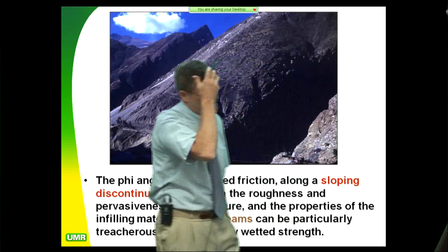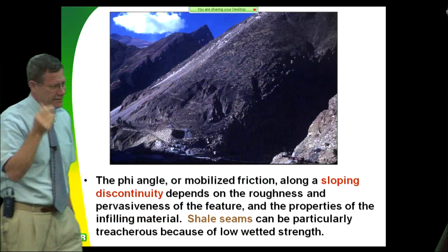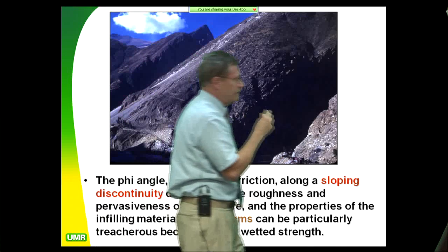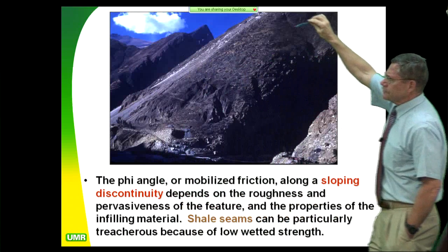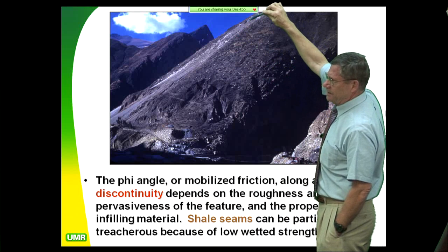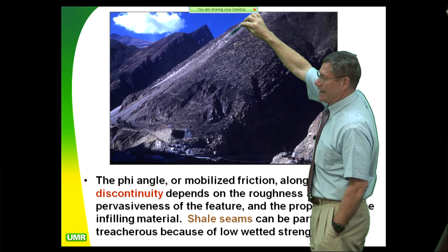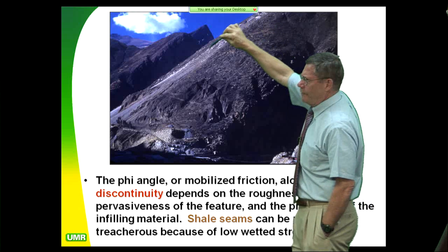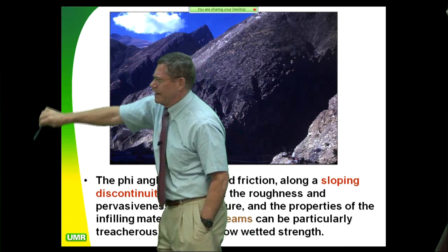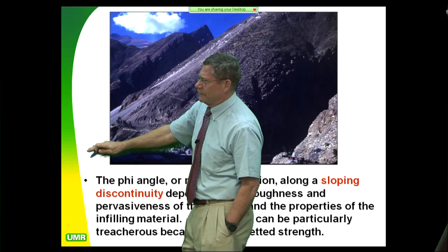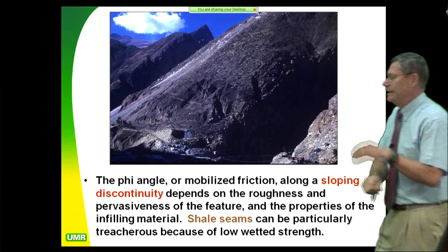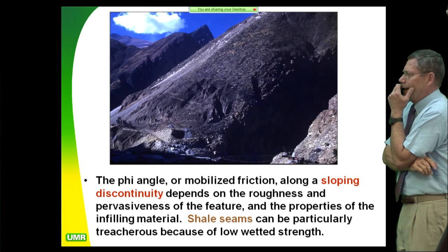Here's one I worked on in South America, where everything's 100 times bigger than in the United States. And what you're looking at here is a shale seam in a bedded sequence of limestone. So this is all limestone. This is a shale seam about 1 meter thick, not even that, 60 centimeters thick. And the whole mountain slid down this thing, and huge landslide dam down here. And then the river filled up behind the landslide dam and then blew it out before I could even get down there to help them on it.